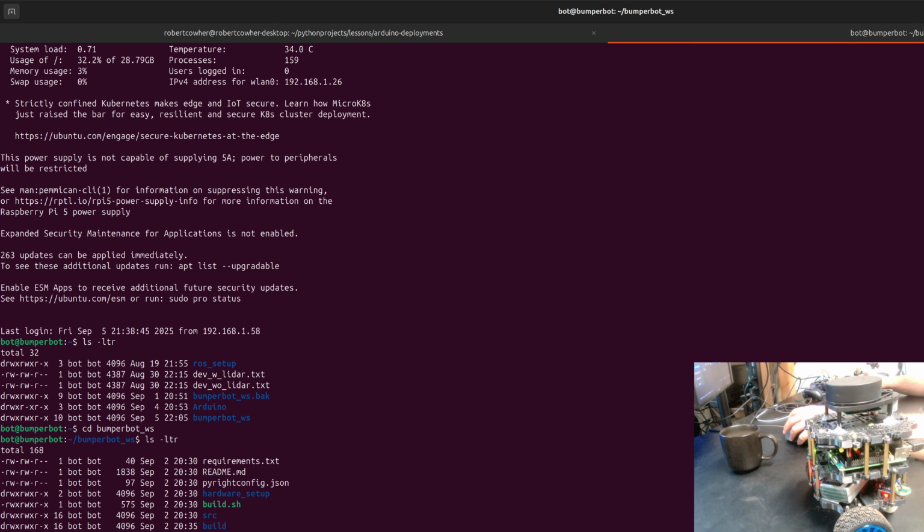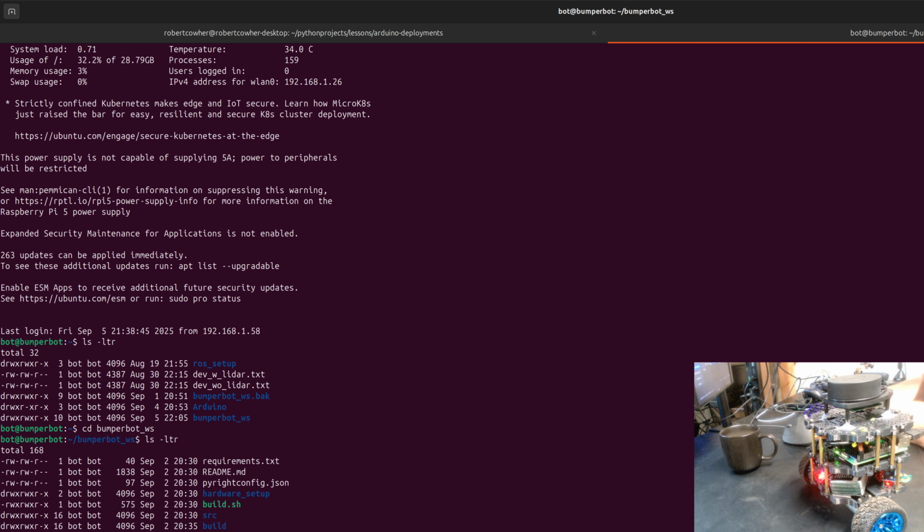And that update Arduino script is just what we saw. It's a compile command pointed at, in my case, a robot control directory, and an upload command pointed at that same directory with the Nano fully qualified board name. And that's really it. So this process lets you effectively take your computer out of the direct connection loop. It lets you use whatever IDE you want to work on your Arduino board, and then you're able to script the deployment of your Arduino source code. And I think that makes your workflow a lot more flexible.